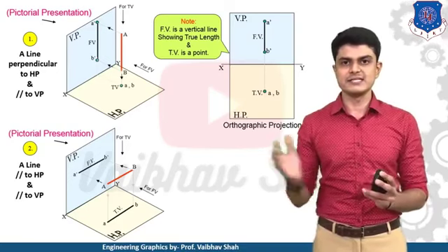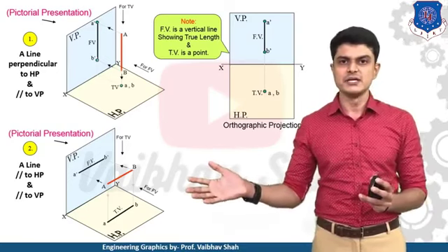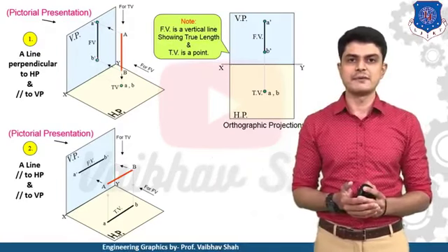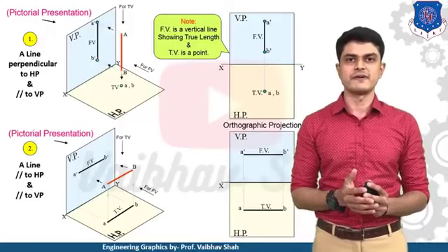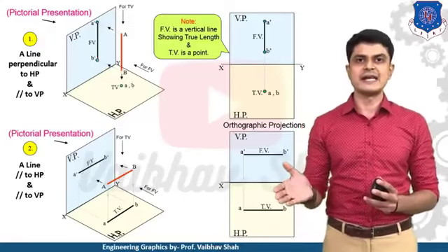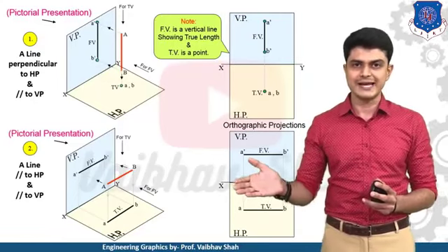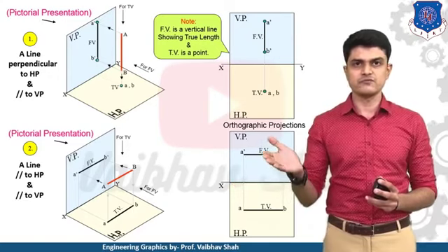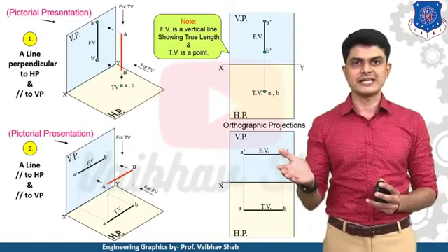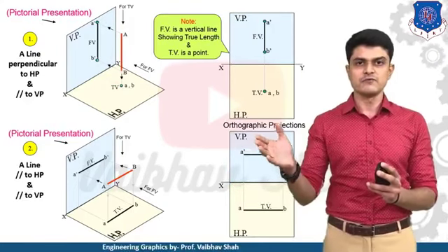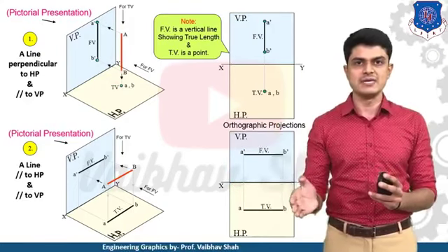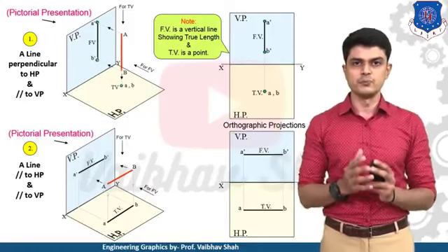So now once again, these views are in three-dimensional format. We will try to convert these views into a two-dimensional, clearly understandable format, which we need to actually draw in our examinations. So this is your final view in which we need to draw one XY line. Above the XY line you need to draw the front view just parallel to your XY line like this, A dash B dash, and you need to draw just below your front view in the same position AB, which will denote the top view.